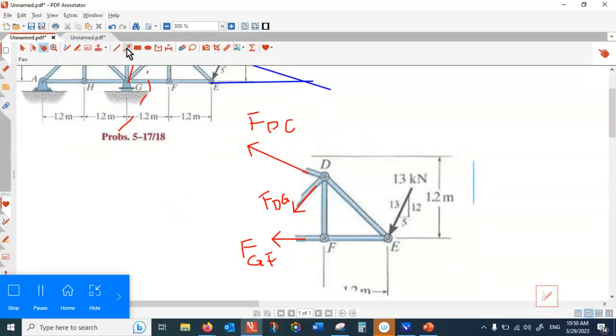So when you are breaking this force into two components, you have to break that into a vertical and a horizontal, right? So vertical is 13 multiplied by cos of this angle, which is 12 divided by 13. So that makes the vertical equal to 12. And the horizontal becomes 5. So now this doesn't exist anymore. Everyone happy with that?